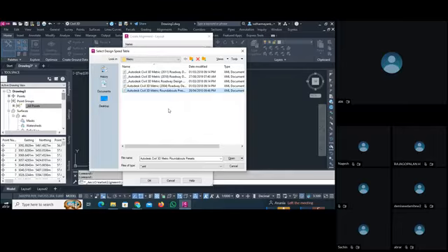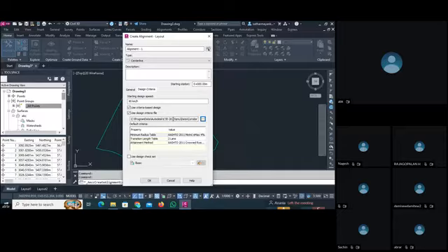But it is still our priority that we have to check all the codes where we are working. So you have to select any code from here, and whatever code you select, you can check here. I select the AASHTO 2011 metric e maximum 4%. The transition lane table is a 2-lane road, and a crown road method is used for this 4% elevation method of this code.